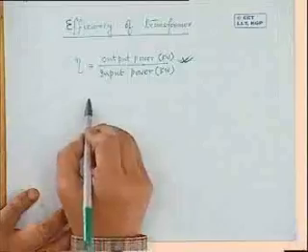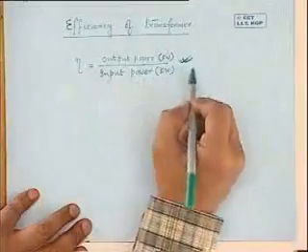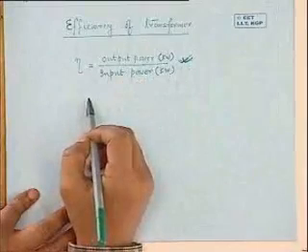During the open circuit test, it is only the core loss. During the short circuit test, it is only the copper loss. Both of them act together when the transformer is loaded. And we will show you that in some other testing conditions this can also be realized, perhaps in a Sumpner test like that. Let us forget it now; we will take it up at a later stage.